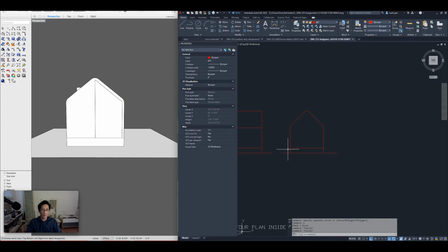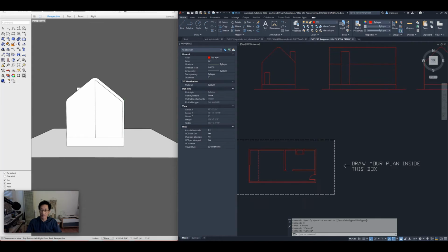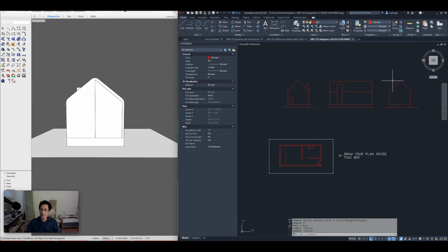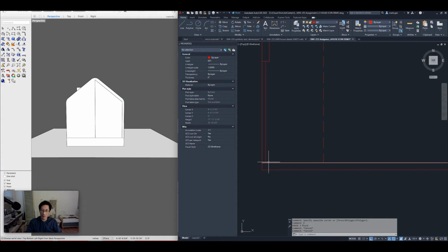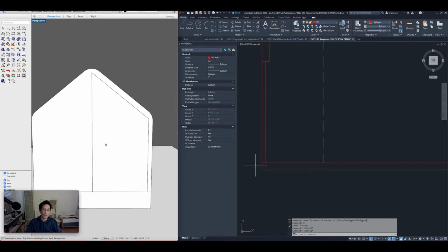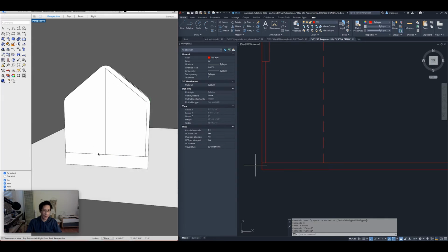And if we remember, according to the plan, this edge of it, the one that would be underneath the apex of the roof, is right in the midpoint of that wall. And we can see also that this wall comes through to create that other line. We should go over to the Rhino model and let's check some dimensions then. So first of all, let's double check that that really is the midpoint. So if this is 20 feet across here, that should be 10 feet. So DI from here to here, yes, that's 10 feet.